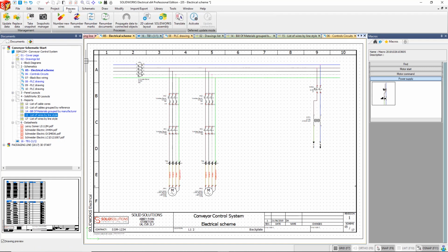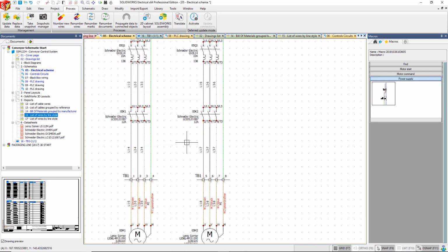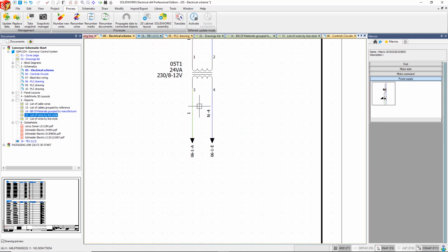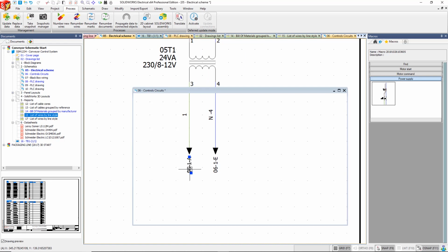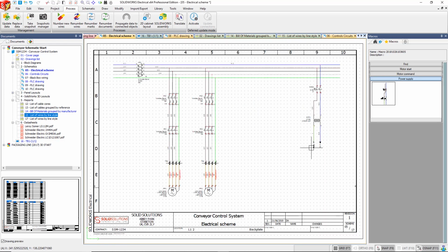We can also number the project. I talked earlier about the formulas that are used. We can just click a button, it reads in all those formulas and gives everything a unique ID in the project. Phase 1 to 3, you can see, have their own prefix, L1, L2, L3, whereas other wires are maybe just numerical. The numbering continues across the project and is all synchronized really well within the package. So it's saving you a lot of time and effort. A lot of the manual tasks that you may be used to in packages like AutoCAD and DraftSight are all automated in SolidWorks Electrical Schematics.